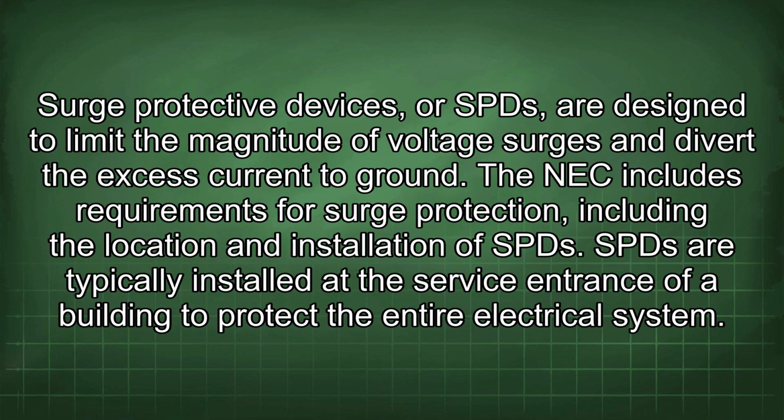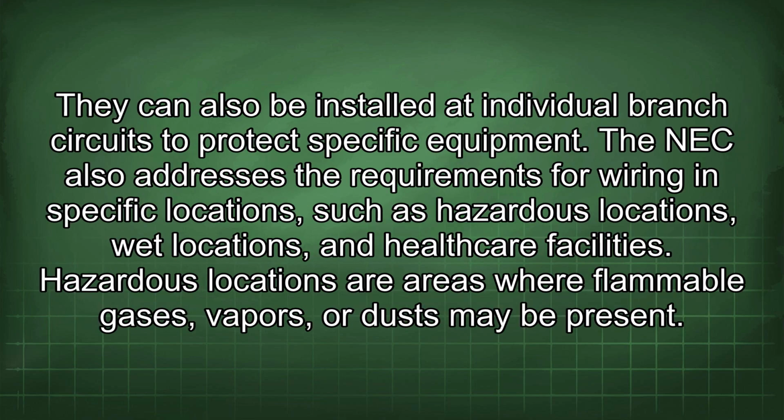Surge protective devices, or SPDs, are designed to limit the magnitude of voltage surges and divert the excess current to ground. The NEC includes requirements for surge protection, including the location and installation of SPDs. SPDs are typically installed at the service entrance of a building to protect the entire electrical system. They can also be installed at individual branch circuits to protect specific equipment.